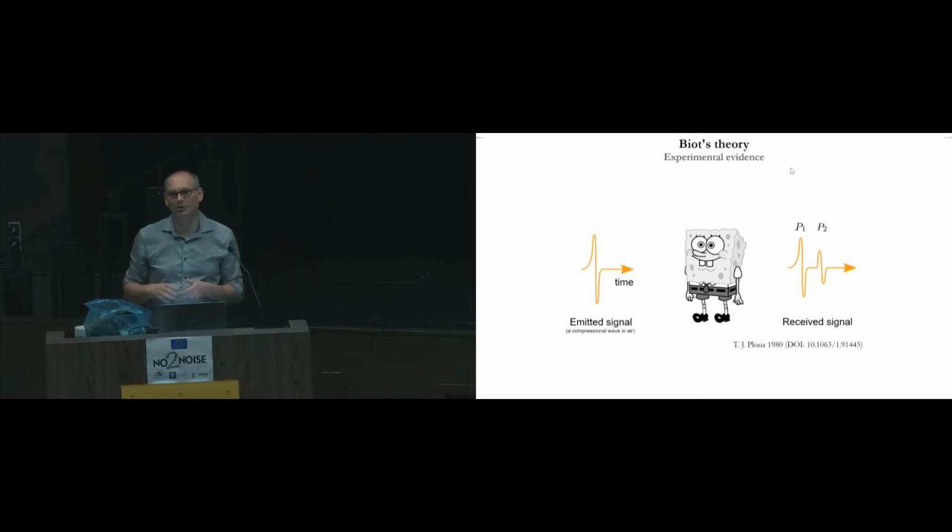Three waves because I have one which comes from the compressional wave inside the air, inside the porous material. Another one coming from the compressional wave inside the solid part of the porous material, and the last one is the shear wave in the skeleton of the material.